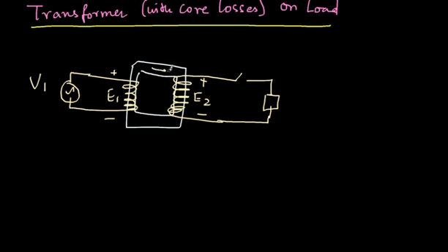And here the flux is fine, and then when the switch is open, the current here we denoted as I naught. Okay, and then we had the vector diagram for this, that is I naught and V1 are not exactly 90 degrees apart, but I naught is nothing but IW plus I mu, that is the vector addition, and as a result of this we get I naught and V1 not being 90 degrees apart, and so on. Now we'll discuss what happens when this is loaded.